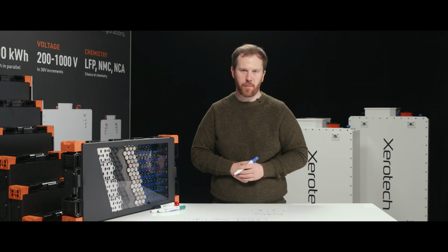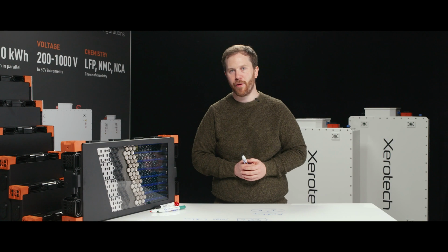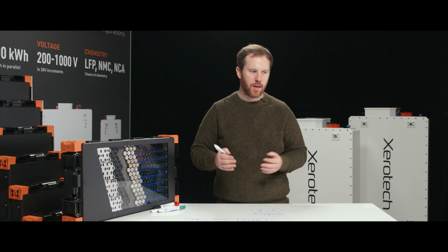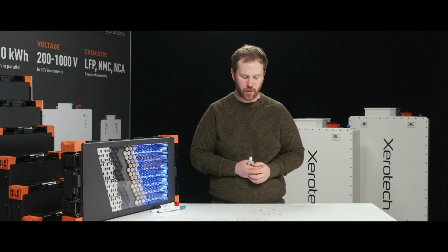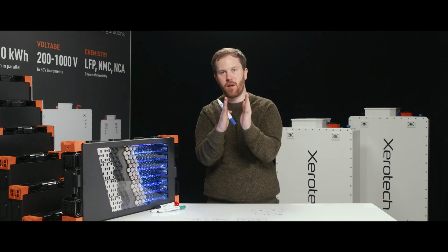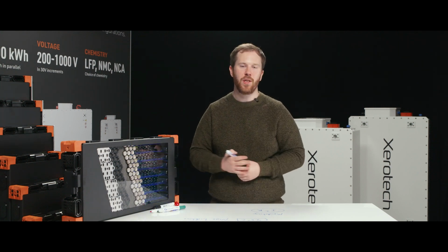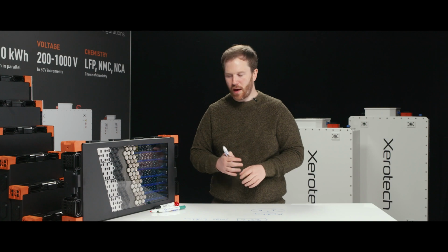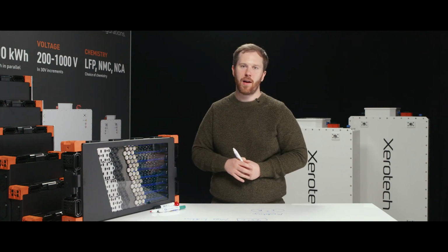But for high performance battery systems, supercars, fast charging, or some of the ones that are overlooked, hybrid applications, diesel electric hybrids in most systems that are coming in the next 5 years, they will definitely need thermal management, because these batteries are much smaller to handle peak loads. So they're usually operating at much higher discharge rates and C rates. So having highly effective thermal management is a critical enabler for hybrid battery systems.